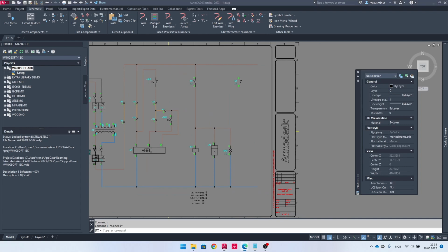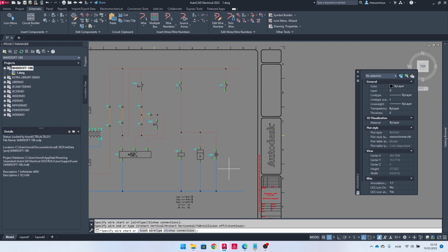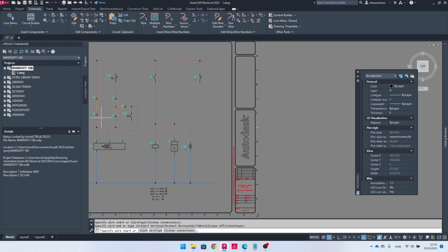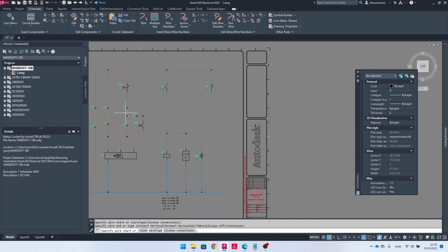And let's just do the red lamp as well. It is going to be connected just below this one. Well, almost. We have some terminals for the lamps for the remote panel if we have that one. So we need X1, 8, 9, and 10 now. They should also be jumpered. Of course they should be.